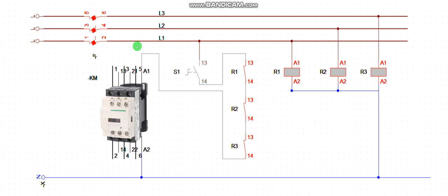Now, let me isolate one of the phases so that you see that each of these will create an open circuit, thereby opening one of the respective contacts. Let's do that now. So I take away line 1, then let's simulate again. Now 2 has closed, 1 refused to close, and the contact is open. So if I energize here, the contactor cannot close because the phase has failed. One of the phases has failed.